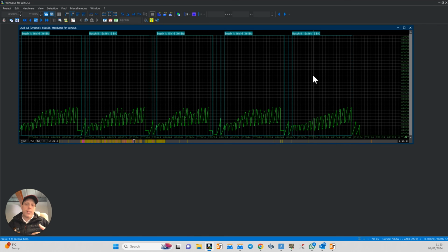So if you're requesting 500 newton meters at 1600 rail pressure, 1.8 bar, the ECU is going to try and use the sensors to move the wastegates and things like that to add more fuel pressure to try and do what you're asking it to do.